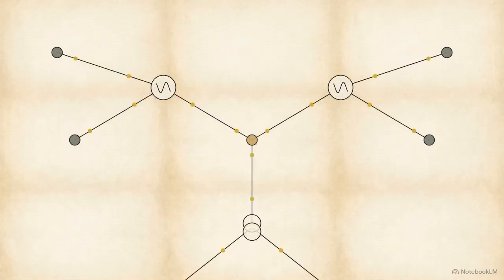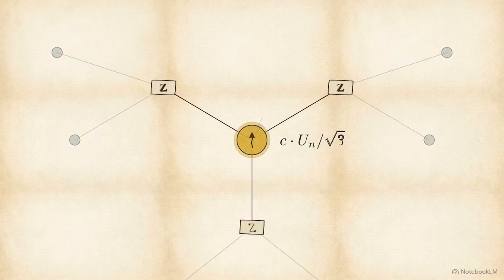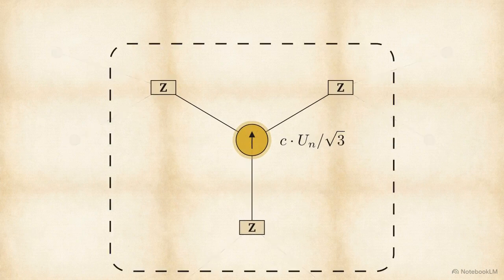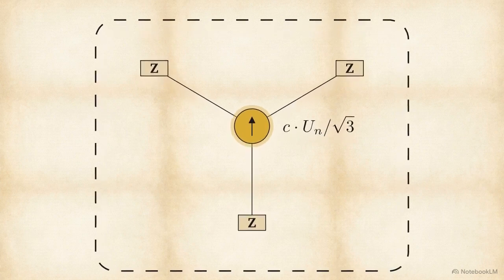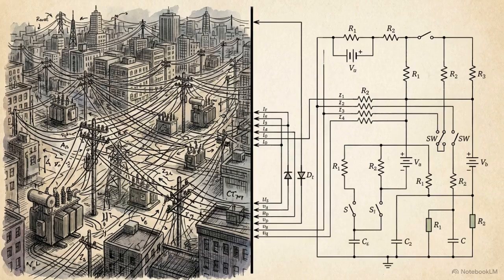This method replaces every active dynamic in the grid with a single, standardized mathematical topology. By isolating the fault location this way, the standard provides a conservative and repeatable calculation that remains valid regardless of fluctuating grid conditions. Replacing the reality of a live grid with an artificial but mathematically rigorous equivalent circuit creates a standardized baseline for safe equipment selection.